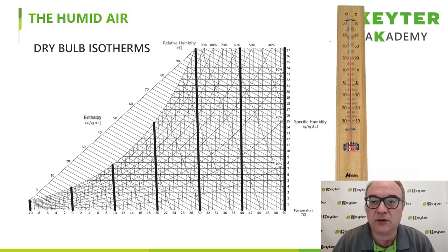The air we have right now around us is air that has humidity. It will always have humidity. Having dry air is very complex. We can almost say it's impossible. A very deep drying process would be required, but we call it a dry bulb because its surface is not moistened with water. This thermometer is going to display the dry bulb temperature, which would be the x-axis of the diagram. And if we draw perpendicular lines, completely vertical, all the lines share a variable with a constant value, in this case 40 degrees of dry bulb.